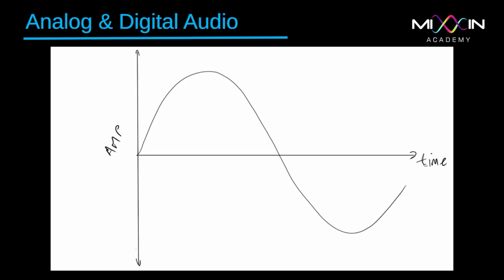In order to digitalize this analog signal, which is continuous, as you can see, it's a continuous voltage change, stronger in one direction, falls off as we talked about, and then stronger in the other direction, then falls off and back, and so forth. The way a computer would digitalize this signal to actually remember it would be to divide this timeline into regular intervals.